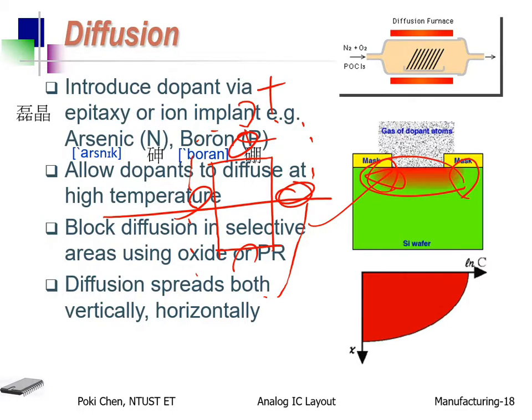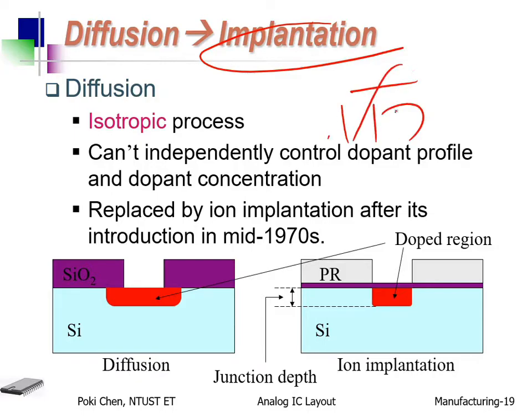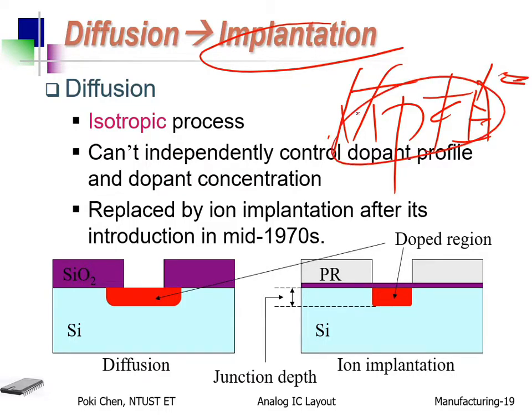More often than not, such a side effect, side diffusion, is harmful for your performance, right? How to control it as well as possible? You need to change the way of doping. So humankind created implantation. For implantation, we use ions. We call it ion implantation.